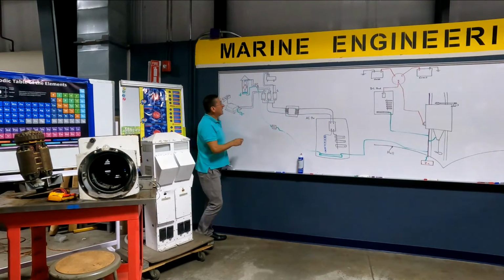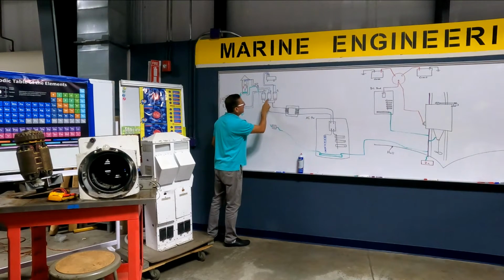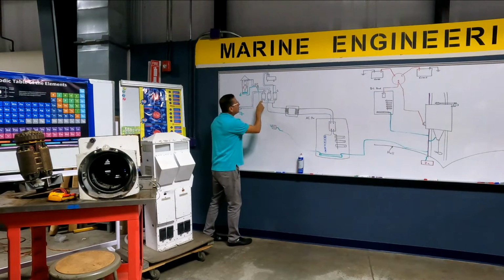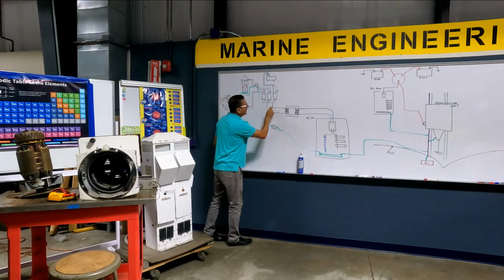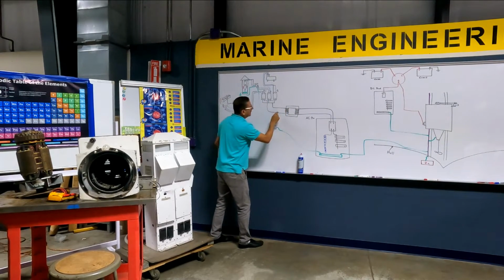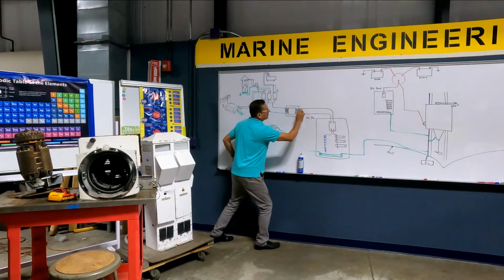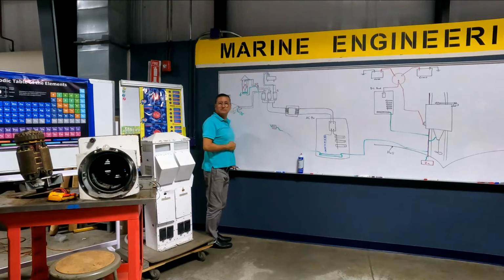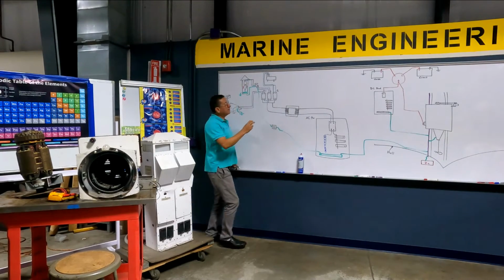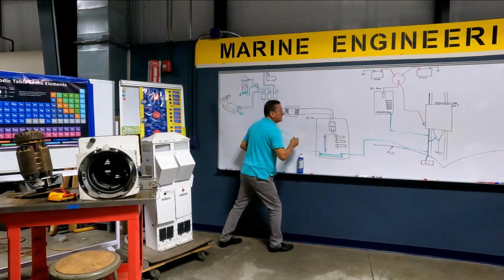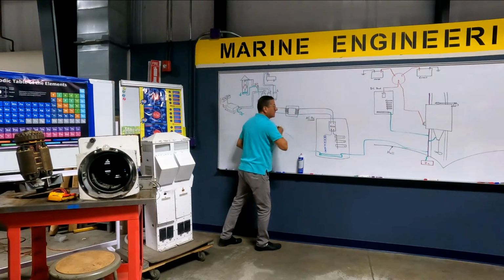It's simple. I am going to connect all the hot lines together and all the neutrals together. From the common connection of hot lines, I enter one transformer, and after the transformer, I have hot line and neutral. The hot line and neutral enter the main breaker of the AC panel.